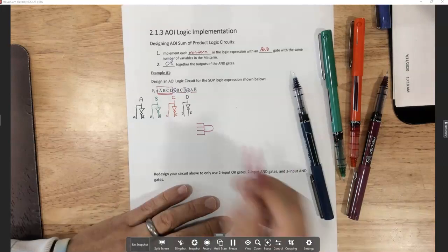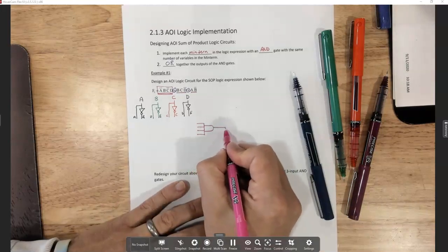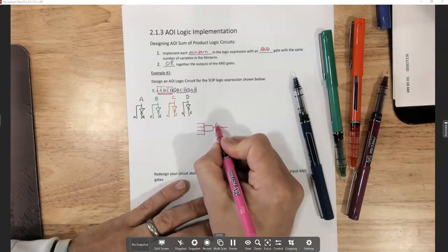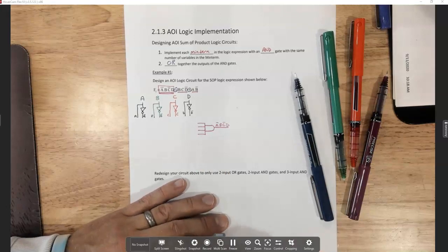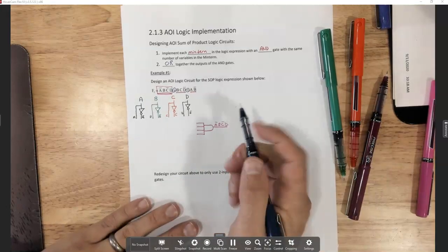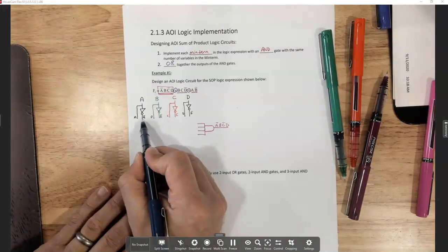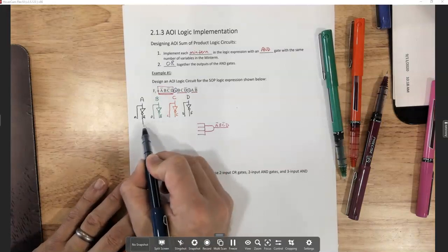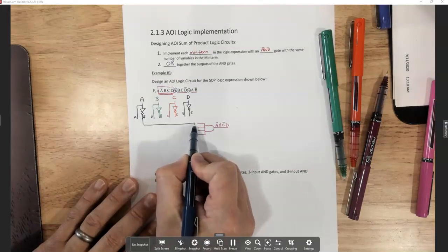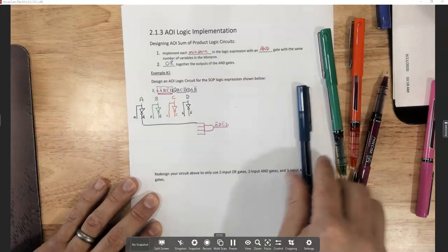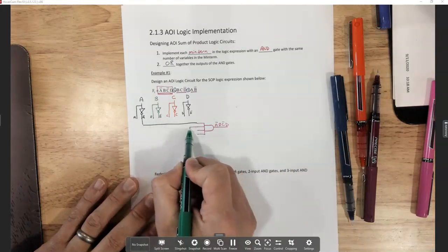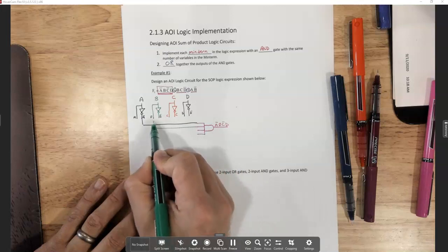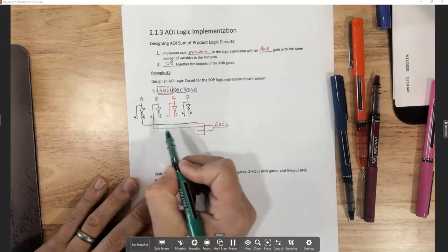If I do that, that is how I'm going to create the signal of not A, B, not C, D. Okay? So I need not A, which means I'm going to grab the inverted A right here. And then I need B. So coming this way, I'm going to take this. I'm going to try to keep everything nice and vertical and horizontal.